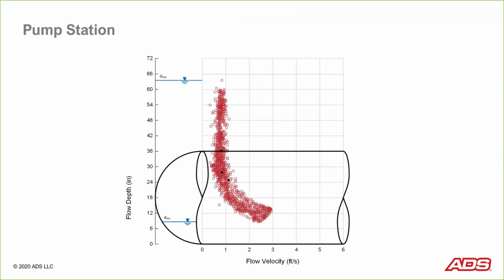The first thing I want to do is apply a Manning curve to this. And I'm going to use the design method. So that means I went back to the municipality and I said, can you tell me the slope of this sewer? And then I assumed the roughness value and I plotted this curve. And you'll notice that the data comes close to this curve but doesn't quite agree to it, which tells me that this data is all either in backwater condition or very close or briefly in uniform flow conditions.